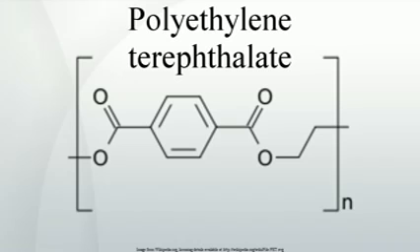Degradation. PET is subjected to various types of degradation during processing. The main degradations that can occur are hydrolytic, thermal and, probably most important, thermal oxidation. When PET degrades, several things happen: discoloration, chain scissions resulting in reduced molecular weight, formation of acetaldehyde, and crosslinks,